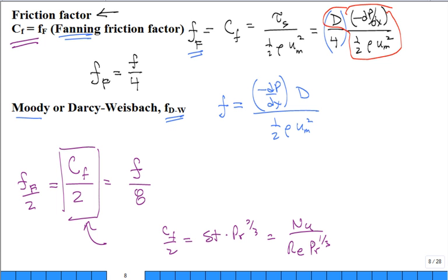So in the hunt, the challenge to find a Nusselt correlation for a lot of problems in internal flow is just take C sub f over 2 multiplied by a Reynolds number times a Prandtl to the 1/3. I'm going to build on that in the next slide or two. So that's why we just don't throw out the Fanning friction factor completely.